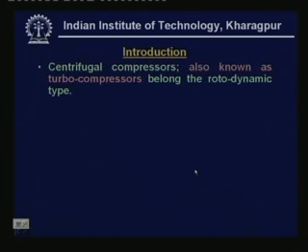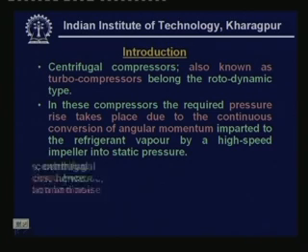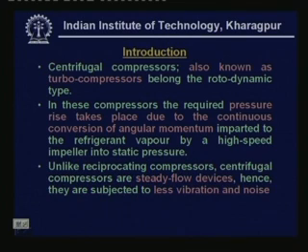Let me give a brief introduction. As you know, centrifugal compressors, also known as turbo compressors, belong to the rotodynamic type. In these compressors, the required pressure rise takes place due to the continuous conversion of angular momentum imparted to the refrigerant vapor by a high speed impeller into static pressure. Unlike reciprocating compressors, centrifugal compressors are steady flow devices, hence they are subjected to less vibration and noise.